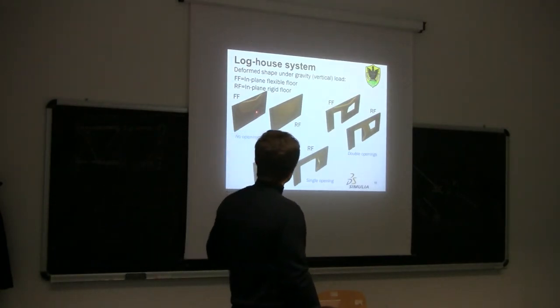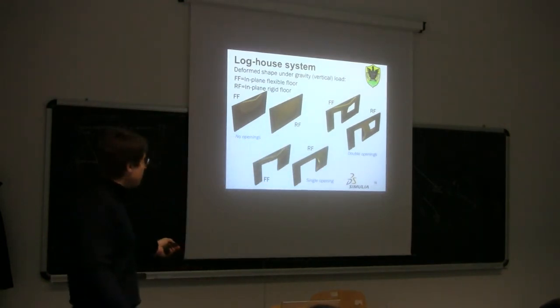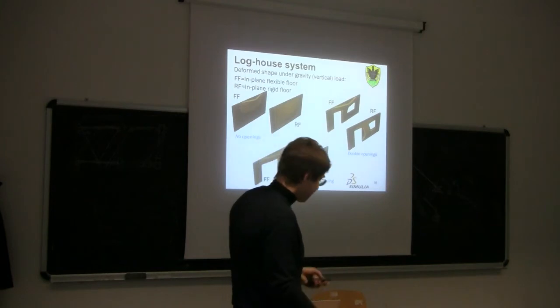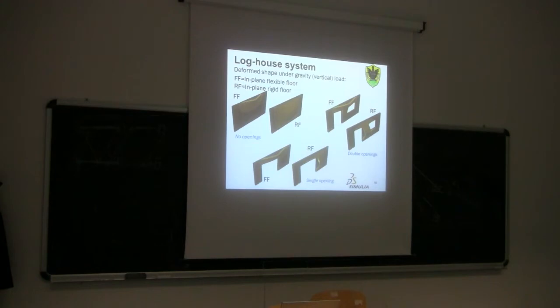So, as you can imagine, having a solid wall is in some way okay, but having some holes, like a door or a window, may create a serious problem, particularly, as you can see here, in this part of wall. In fact, what provides some lateral restraint, in some way reducing the flexural buckling, is the connection between one wall and the other wall. So here it is not shown, but here there is another wall perpendicular, and also here there is another wall.